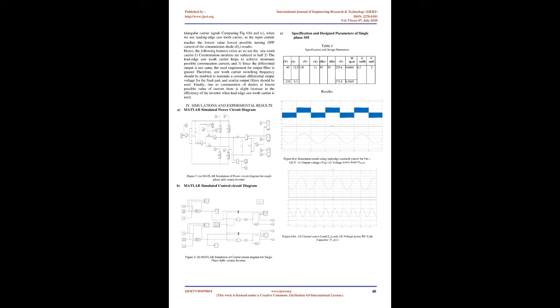Thus, we implement the modified SPWM, MSPWM, technique, which has a constant charge and discharge period of inductor L, and by setting the minimum reference signal value at the minimum carrier signal value it gives lower voltage stresses. 3. Modulation using different carrier signals.